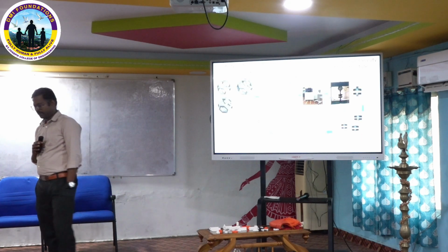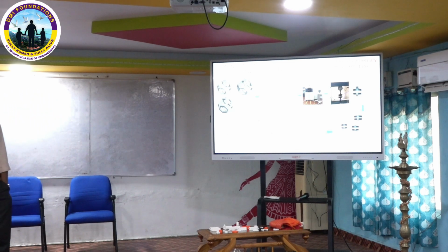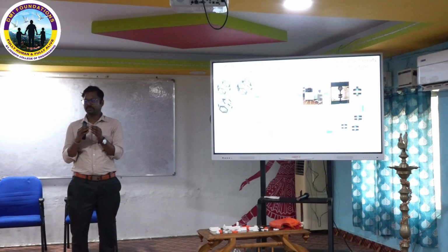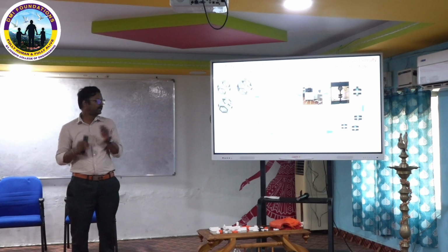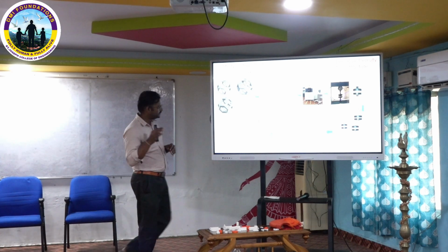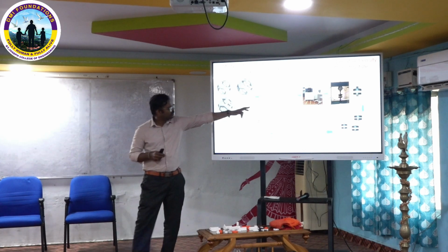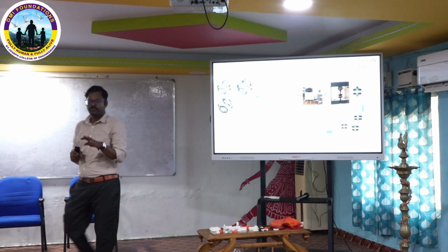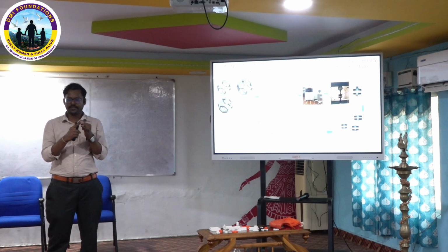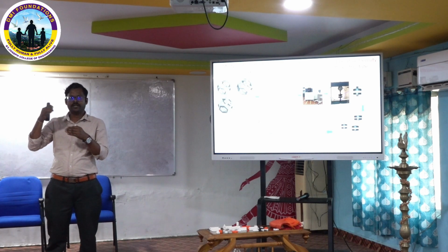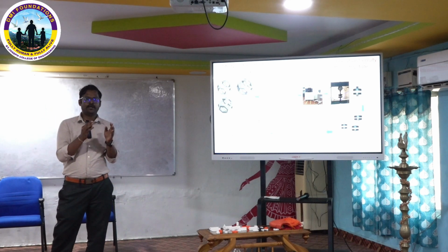First, with polymer additive manufacturing, SLS technology, I fabricated lattice structures to study how laser process parameters impact the properties of lattices. I did this work with the help of lattices. Actually, what are laser parameters? The machine we saw yesterday has 240 parameters inside, like laser parameters, beam offset, how the material has to flow, how the laser moves, and how the F-theta lens has to move. For each and every powder, it has its own 240 parameters.